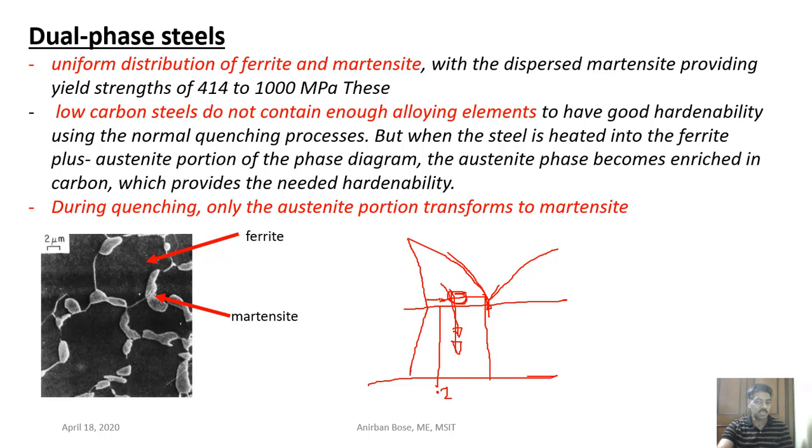But most of the structure in this position is basically ferrite, you can see. Because the opposite term indicates the fraction of ferrite present in the structure, right? If this is R and this is S, the ferrite present is basically S by R plus S, right?